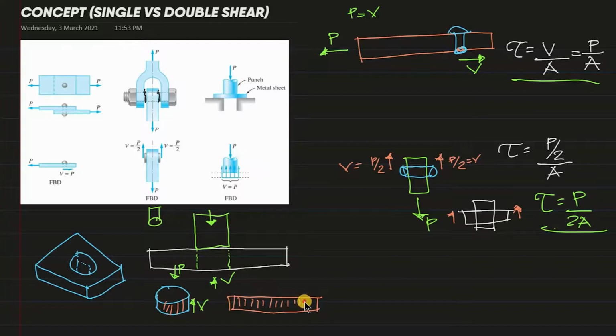So, this is the area na kinakailangan natin para ma-solve yung ating shearing stress, which is equal sa P over sa area natin. And we know that this area is this area. Para makuha yan, circumference of a circle, di ba? And we know that circumference is 2 pi r. And also, alam natin na yung thickness nito is T, okay? So, length times with 2 pi r times T, yun yung area natin dito. Okay? So, ayun lang mga bis.